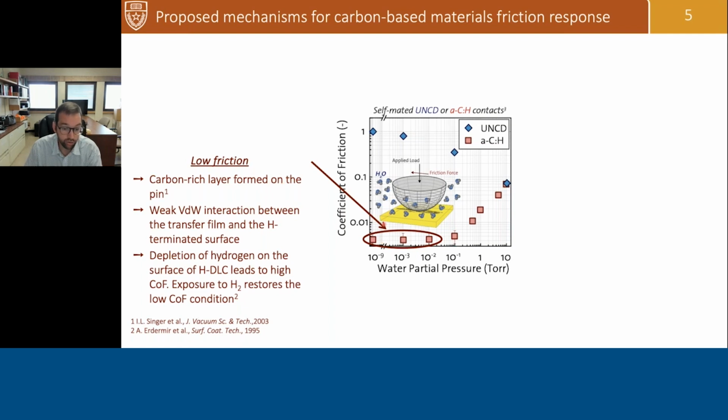In this case, the low coefficient of friction is attributed to the formation of a carbon-rich layer on the counter surface, so the sliding pin, which results in very weak van der Waals interaction between the transfer layer and the hydrogen-terminated surface of a-C:H. In other words, in this case, the velocity accommodation mode is interfacial sliding, which results in a very low interfacial shear strength.